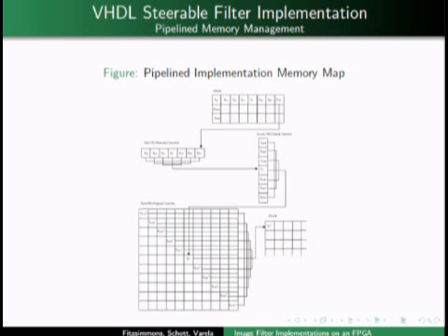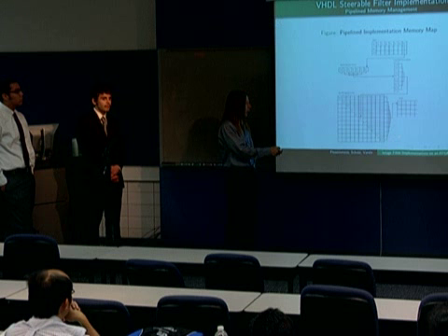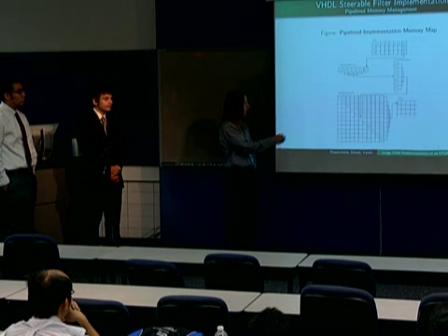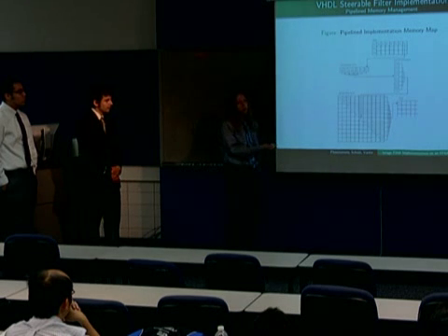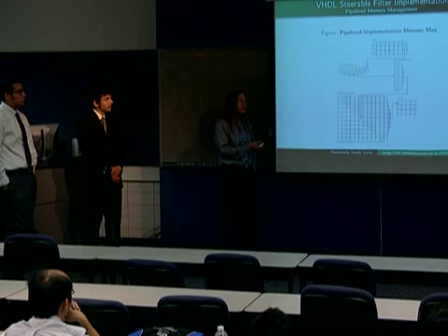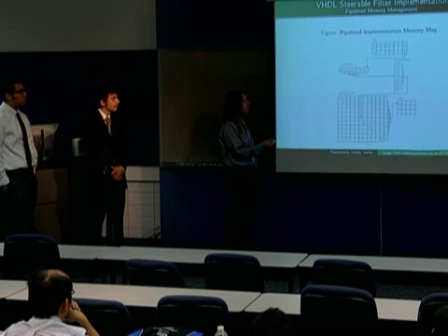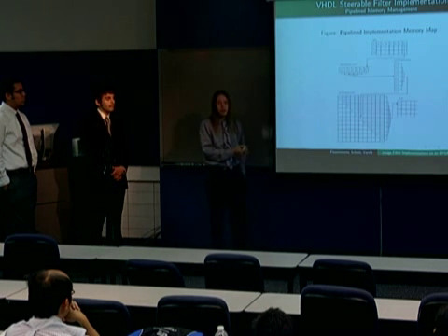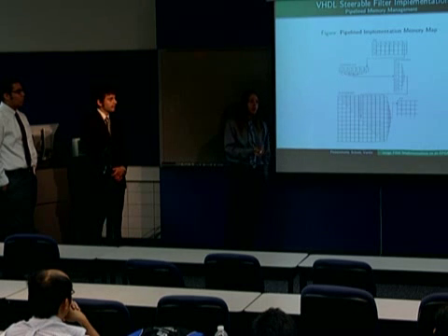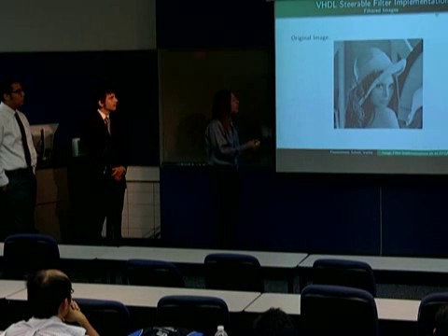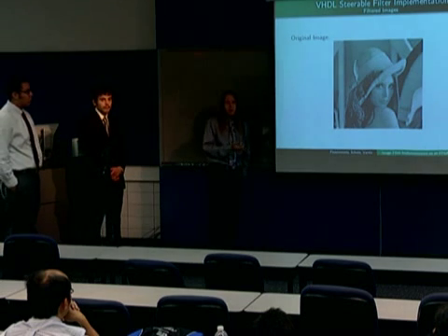So there's a timing difference that has to be accounted for to store it in the BRAM. But essentially, once it has enough pixels, it takes these diagonals and convolves them and stores them here. Then these pixels next to it are shifted over to the side, and then this last pixel comes from here, and then it convolves it and would store it as the next pixel, etc. And this allows you to use the results of your previous convolution in real time to create a near 1 pixel per cycle result. So now I'll show you the results from the FPGA.